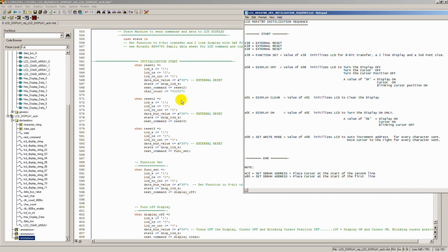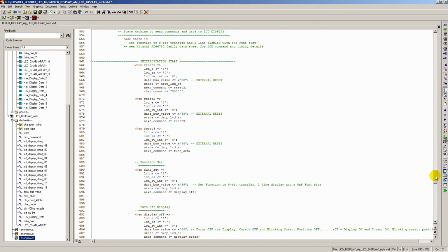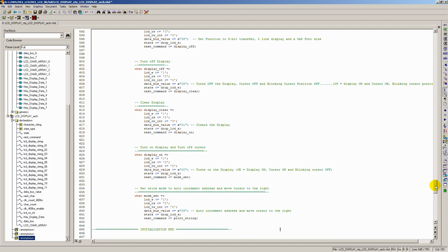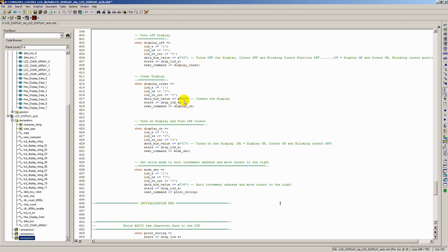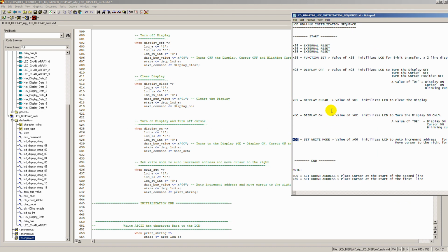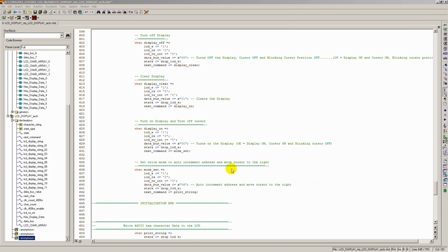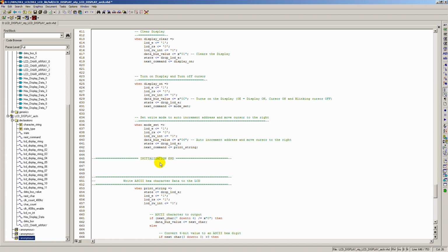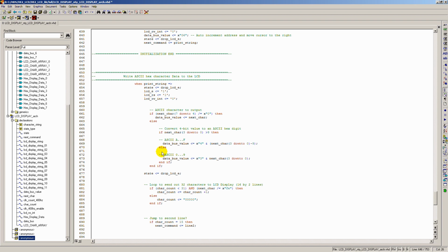You'll see these are the states on the state machine for the initialization sequence, and for each of the 8 states, they are all displayed here. And you'll see how their hexadecimal values map and match accordingly. We have our 08, 01, and 0C, and the final hexadecimal 06, as I had reviewed before. So it's pretty straightforward. That's the entire initialization sequence. All that part of the code is the initialization sequence.